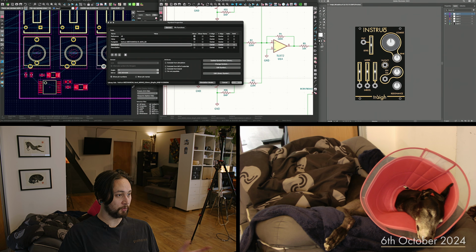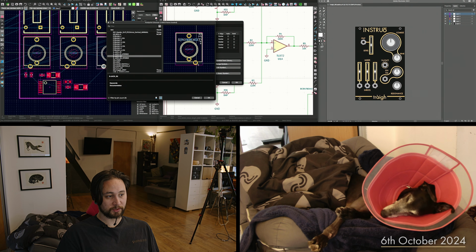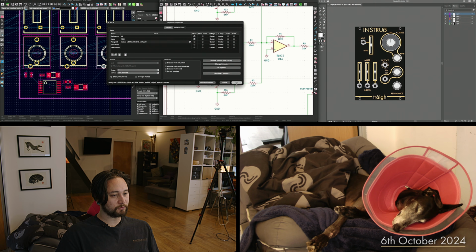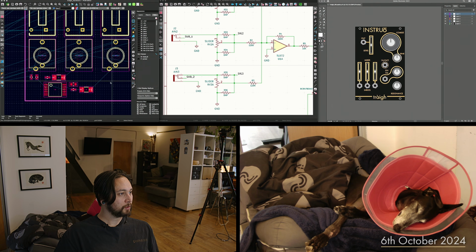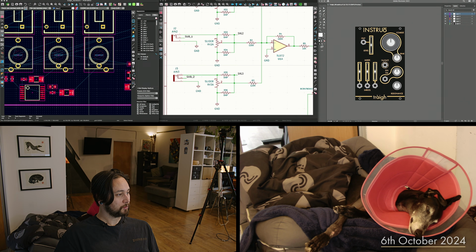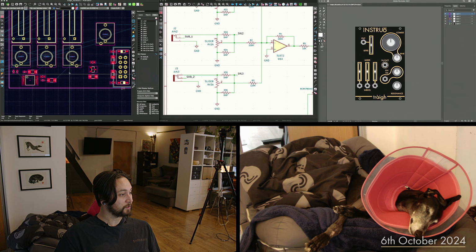I know the name of it, but I could also click on this and search the actual part. So that's the one that I used previously. I'm changing to S2, which has the sleeve pin, the ground pin, over the other side. So do that, save, and back over to the board. And it's this command here, which is update PCB from schematic. I've got that mapped to F13. Take that, boom, flip them over. I'll keep that one where it is, why not? Okay, that's nice and neat, I think.